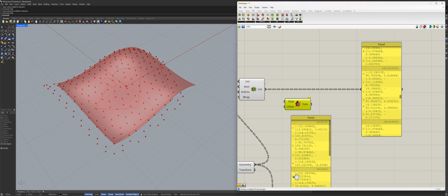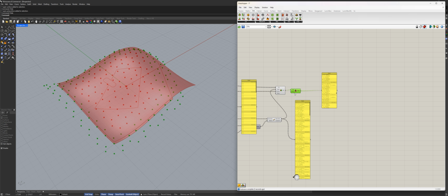You plug the data into your tree and it looks for the paths, and it will call one of the elements. By default, it's set to -1, which means it takes the last one. You can make it the first one, and the amount of offset basically describes how many elements you want to call. So plug that in by default, and bam, here we go. Now we have a proper data structure.